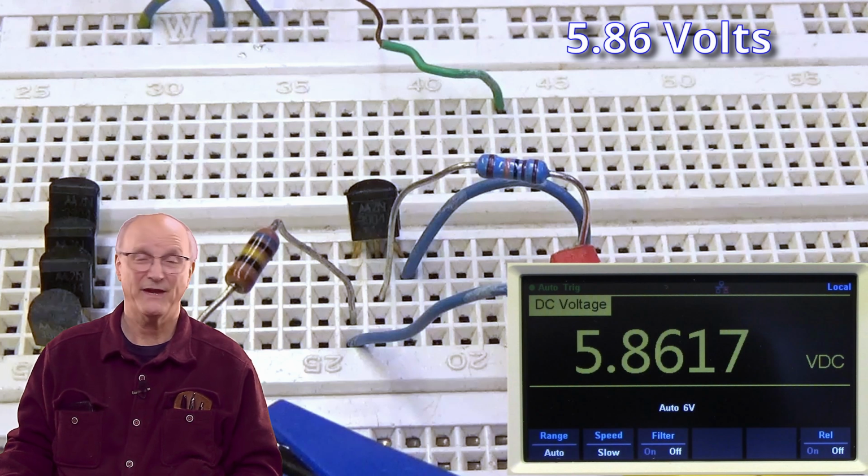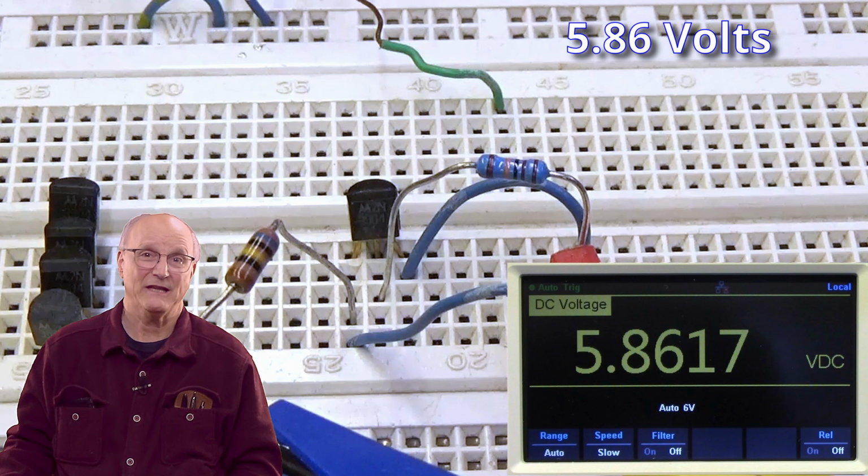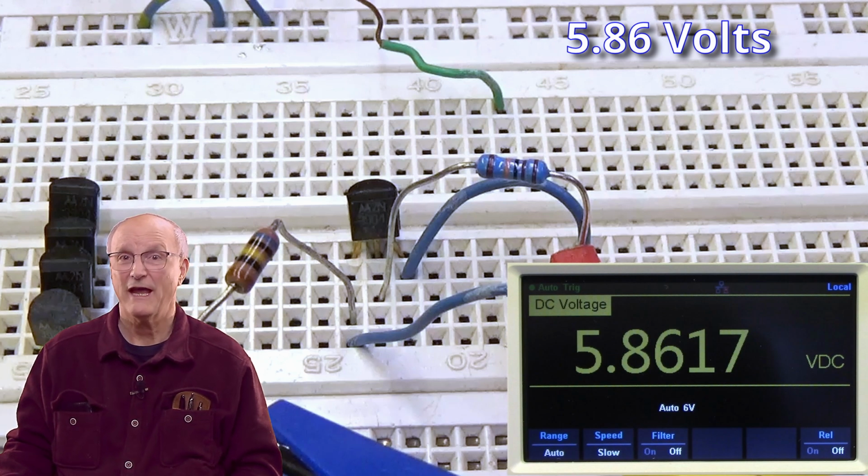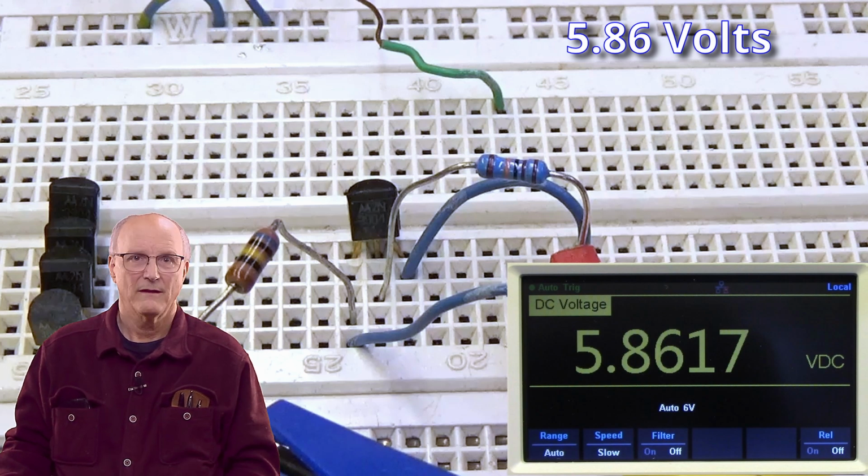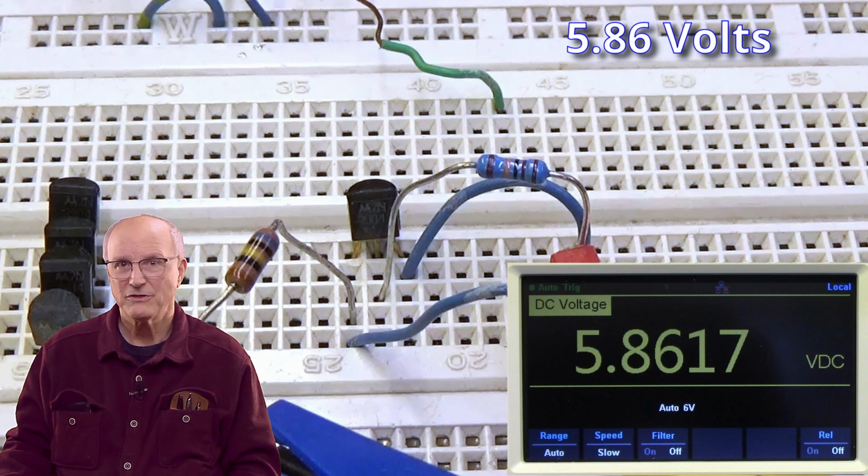But reality hits. The calculation of these resistor values and the success of our bench experiment all depended upon the actual real-world transistor having a DC current gain of 200. In our case, I just happened to choose a transistor that had a DC current gain of around 200 in my random pick from my junk box.